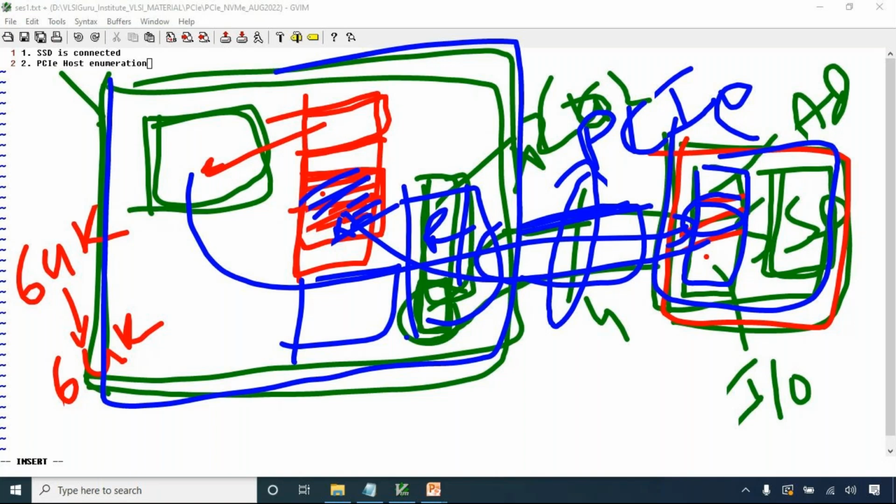Okay, X1 only. So I have a controller with NVMe X1. So I will be using PCIe X1. SATA is X1 too, right? SATA highest is 3.0, which is 6 Gbps. One lane of PCIe Gen 3 is 8 Gbps. Will I get only that much of difference, 2 Gbps, or will it be entirely different? It's more than that.